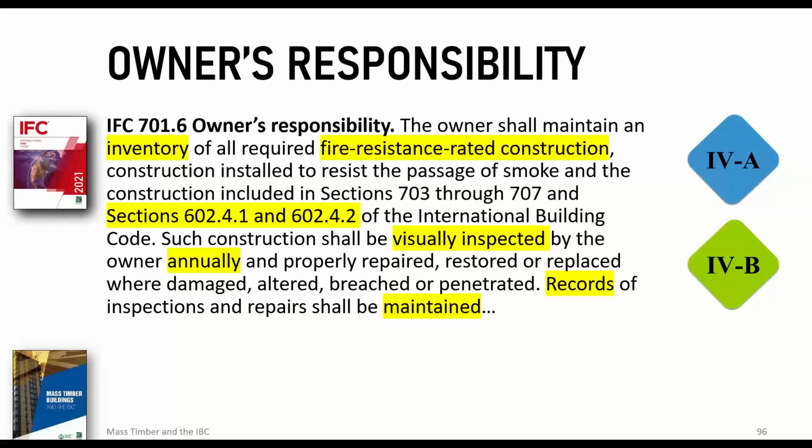I'm just trying to illustrate how building management can do some screwy things once we're not looking anymore, or once they get their C of O. So that was what this was put in for. And what else happens after the building gets a C of O? Verizon comes in, Xfinity comes in, and they start making Swiss cheese out of the draft stopping or the fire blocking. So this would ensure that none of that happens. And like I said, I wish it would apply to all.